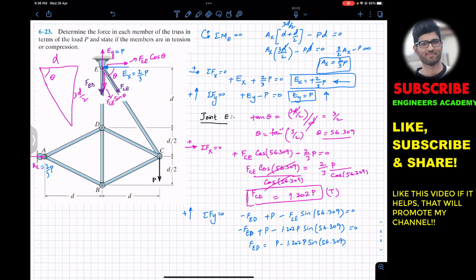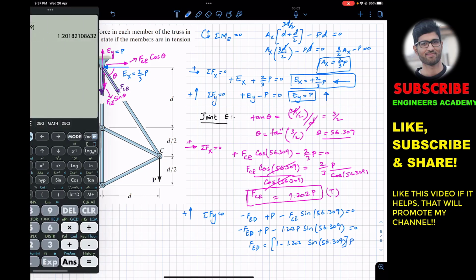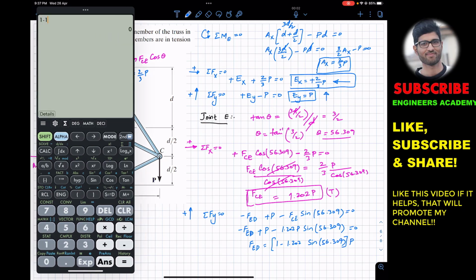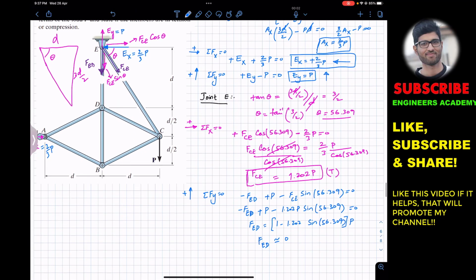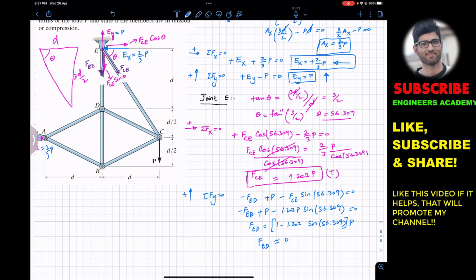We can take P as common from both these terms, so we will have 1 minus 1.202 sine of 56.309, into P. We got this as minus 0.00, which is approximately equal to 0. So FED is approximately equal to 0. This means that the ED member is the zero force member. The ED member is carrying zero load. So FED is equal to 0.